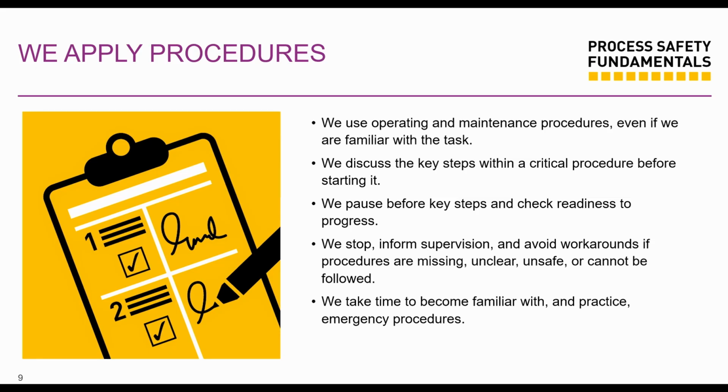So that's a scenario. Also, you're starting, let's say, a distillation unit without using the established up-to-date startup checklist, because stuff is updated regularly, and then you want to resume procedure. But you didn't check your pump alignments. You didn't check that all your valves are properly lined up. One valve may be left open or closed, and this triggers an emergency shutdown. So you don't rely on past experience, especially when it's a critical or emergency procedure. You need to keep that at the back of your mind.